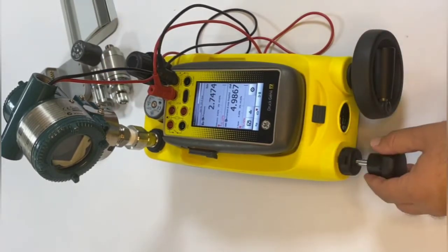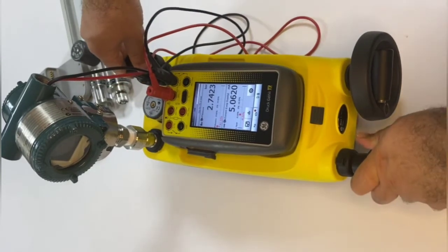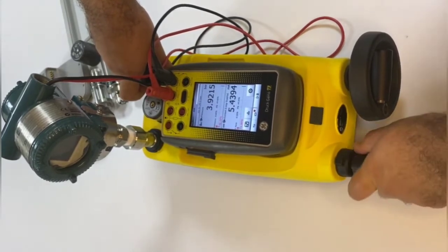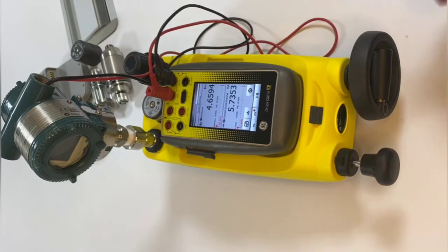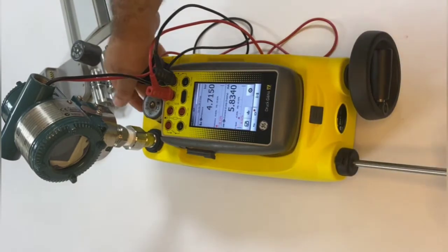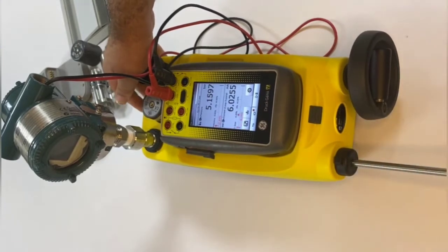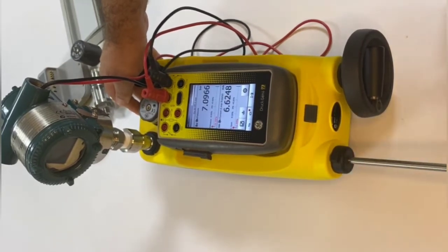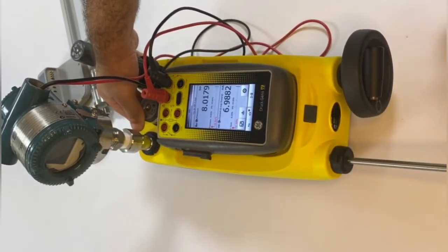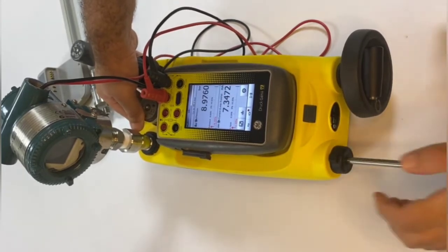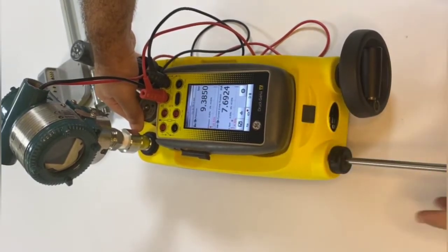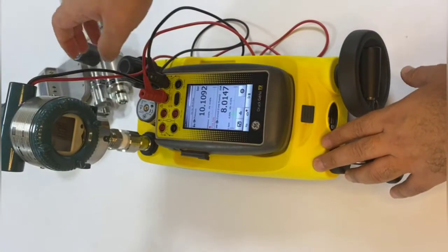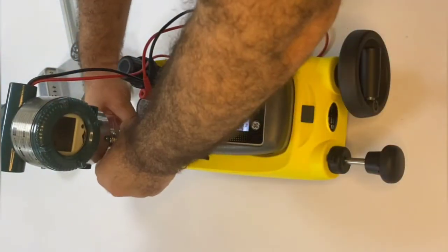Of course, the station is designed for 100 bar. As you can see here, I am putting pressure. Every stroke will put around 1.5 bar. This will allow me to put points in the middle and simply perform a precise calibration between the points. So here I'm using the stroke pump to put pressure. The display is displaying the reading and the milliampere is measured by our system.